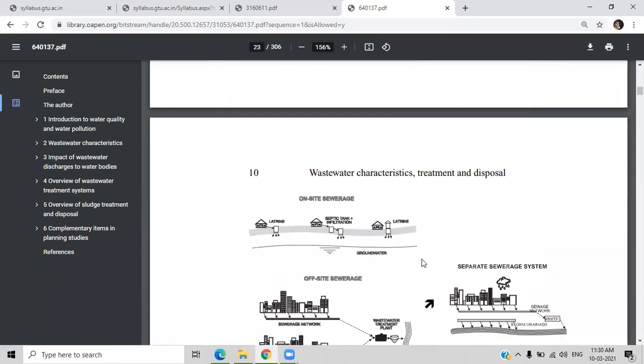So, in warm climatic countries like India, if we design a combined sewage system which contains the stormwater as well as the sewage water, then in that warm climate or in the summer season, the water is deposited in those larger diameter pipes, and due to that deposition, the generation of malodors and mosquitoes is going to take place, or foul odor is going to take place.